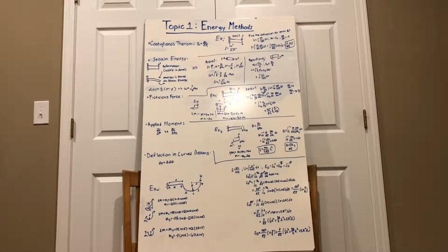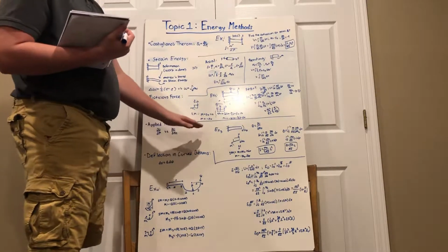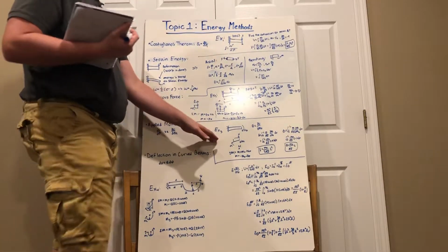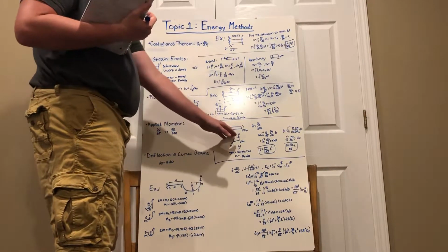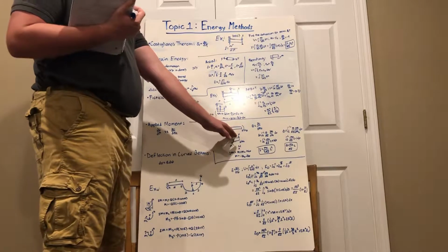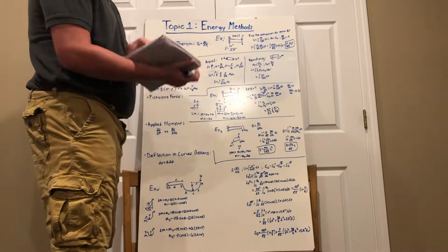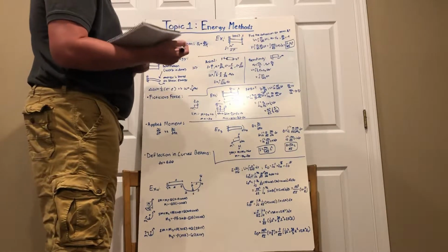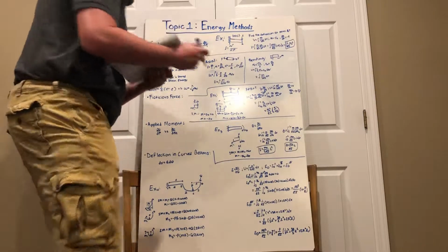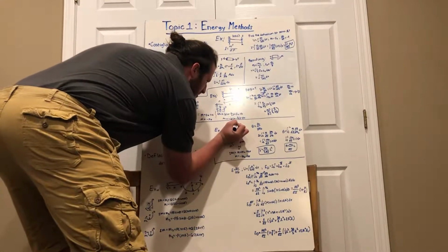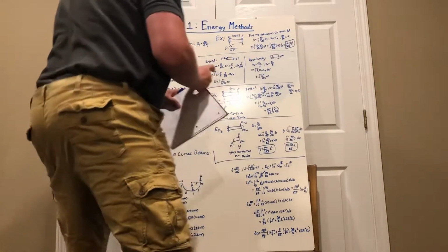As we do that, we see that we could apply the equation in a similar manner. So applying it in a similar manner, we just have this problem here. We're basically going to ask to find the deformation of that beam at the end, but this time with an applied moment instead of an applied force. So here, since we don't have a force, let's apply a fictitious force again. Let's apply this here at the end and call it Q. And remember, Q's magnitude is 0.